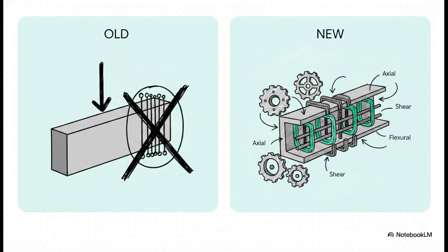We're opening the final and maybe most significant compartment of our toolkit here, the concrete shear contribution calculations, known as Vc. Under the old ACI 318-14, engineers could use a pretty simplified equation for Vc. Basically, as long as there wasn't an axial force present, the actual area of shear and flexural reinforcement wasn't really a major consideration in that simplified equation. But under ACI 318-19, everything changes.